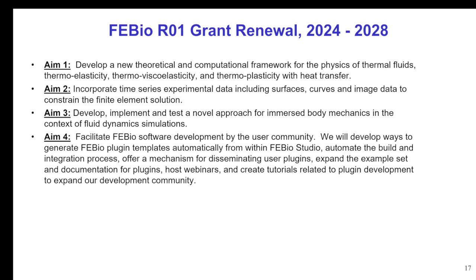And then in aim 3, we're focused on looking at immersed body mechanics in the context of FSI. So the idea that you can have more like a deformable structure that's inside a flow that has its own remeshing going on at the interface between the fluid and the solid.